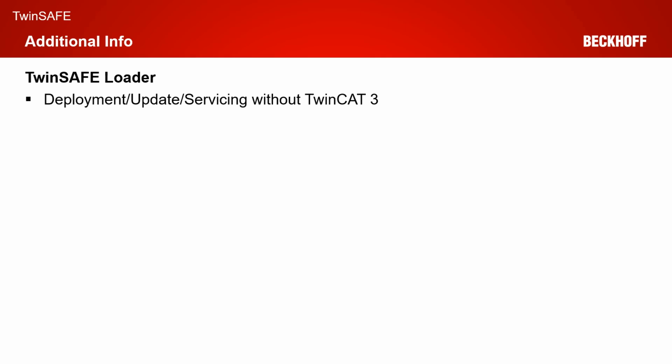So even at runtime, you could choose that Monday, Tuesday, and Wednesday you want to use the hardware inputs, and Thursday and Friday you deactivate them via your custom HMI, which triggers the TwinSAFE loader in the background, for example.